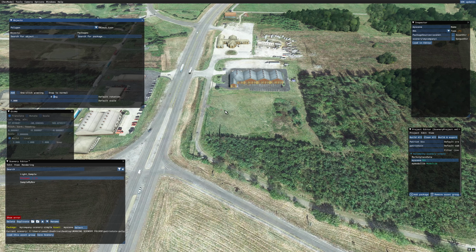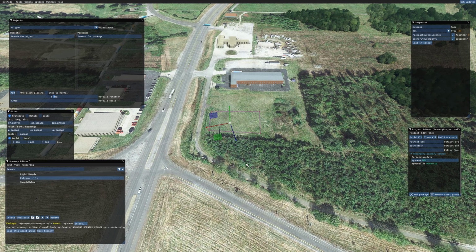And the polygon, you may not be able to see it, but it's following my cursor around, a little red X. And I want to hold the left control key down, and I'm going to keep it down the entire time, and I'm going to use my left mouse button and tick. That set an anchor point, and now I'm going to use my left mouse button again and tick, and tick, and double click to complete the polygon. And the polygon is complete.